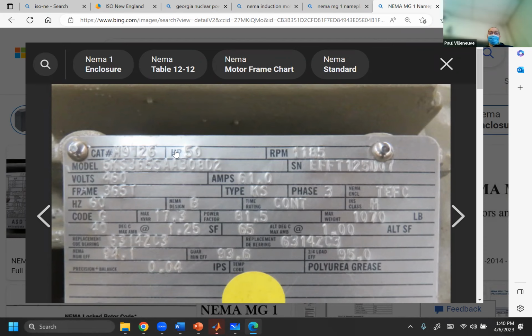Now, for those of you who are interested, if you get into bigger motor sizes, the vast majority of motors you'll come across will be 3-phase, probably 460 or 480 volt. You can get 208 volt, but it's not as common as 480. Once you start pushing about 250 to 350 horsepower, you need to go up to a higher voltage. So once you get to 300 horsepower or so, you're going to get to a medium voltage. It's rated at 4,160 volts.